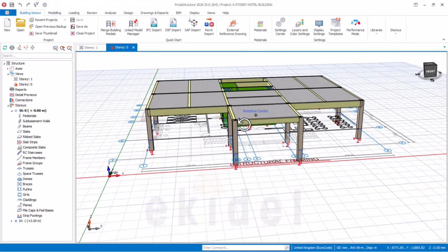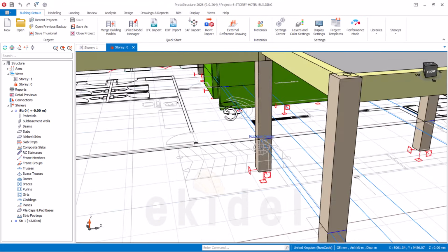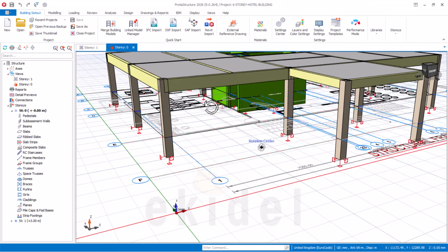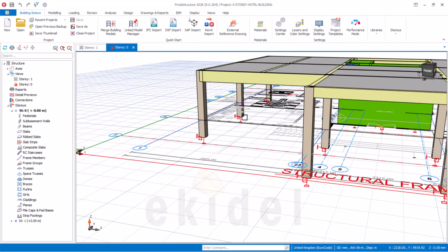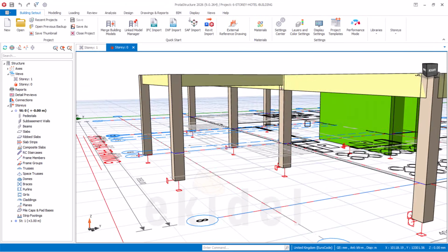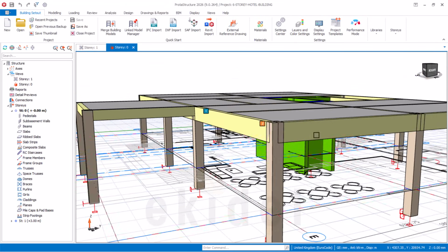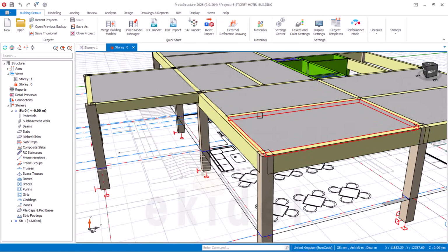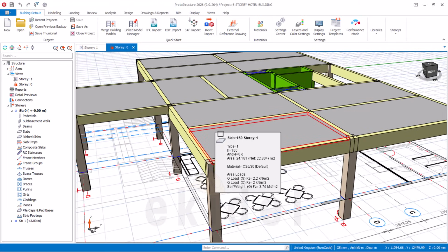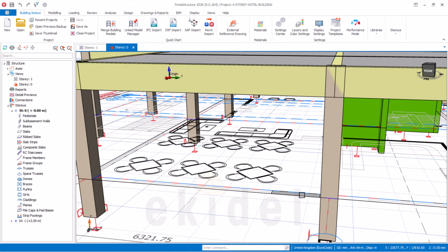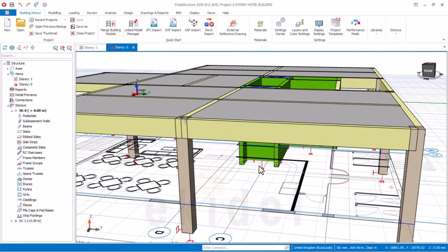You can see the trace of the floor plan directly here. That's because we sent it down on this level. We want to bring this tracing plan up to this level, because we want to model the staircase and also the openings on the wall after adding the wall load. So how do we do that? How do we move this tracing plan you are seeing here from the story 0 down to the first floor or any story?